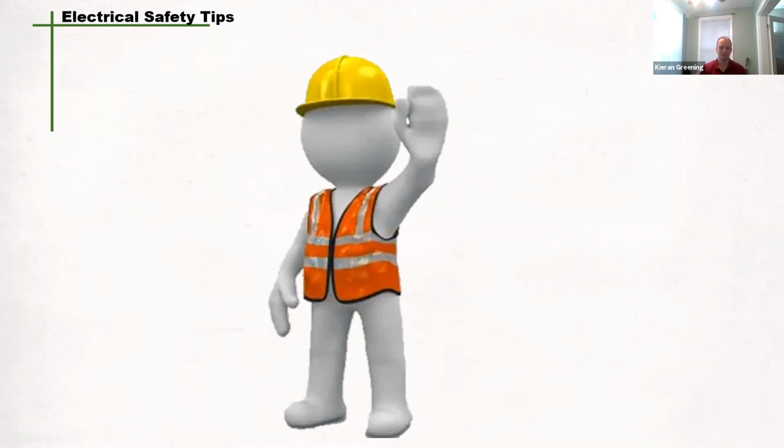So you want to replace those extension cords, or fix them with a qualified person, when damaged. Never use nails or sharp objects to hang extension cords from ceilings or walls. Use brackets or things that are sold to hang the devices, as well as if you're going to drill into the walls, make sure you know where power sources are. Never run electrical cords through the window. Like I said earlier, there are the pinch points.